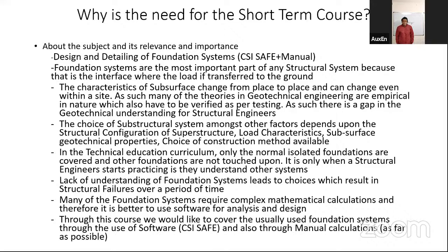The substructure is the interface between the structure and the ground, the earth, where you transfer the loads from your building or structure. So foundation systems are the interface between them. Naturally they become very important because they are the final load transfer point for your structure. If the final load transfer point is not proper, it will lead to problems in your structure as a whole.